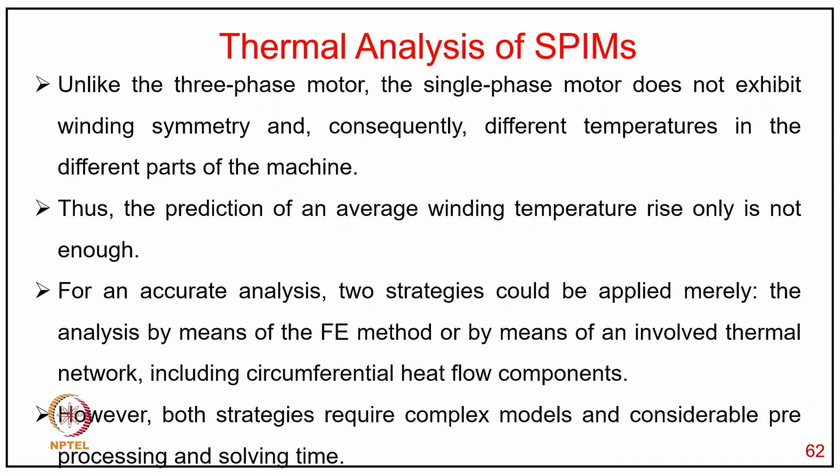Unlike the three-phase motor, the single-phase motor does not exhibit winding symmetry and consequently has different temperatures in different parts of the machine. Thus, the prediction of an average winding temperature only is not enough. For accurate analysis, two strategies could be applied: analysis by means of finite element analysis, or by means of an involved thermal network including circumferential heat flow components. However, both strategies require complex models and considerable pre-processing and solving time.